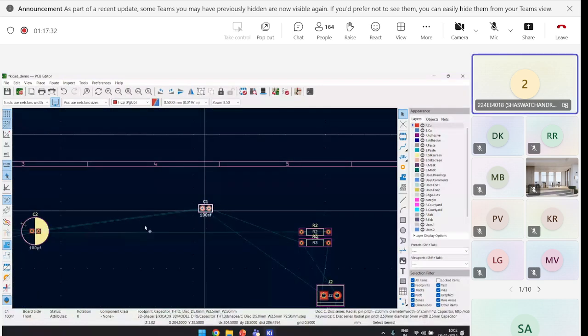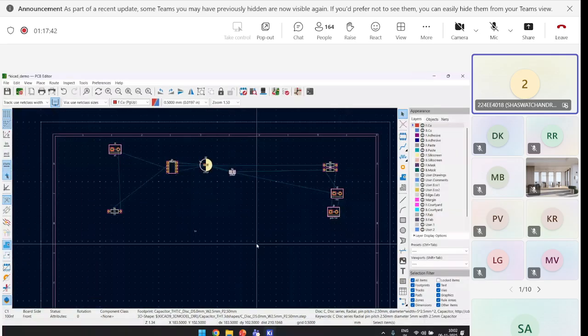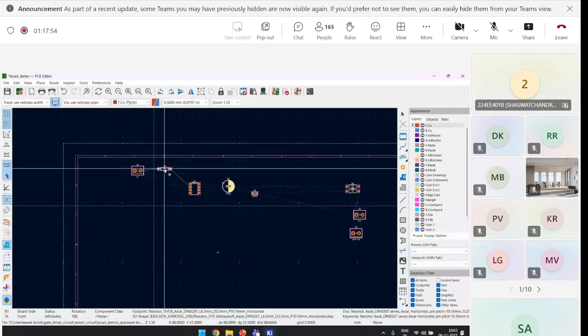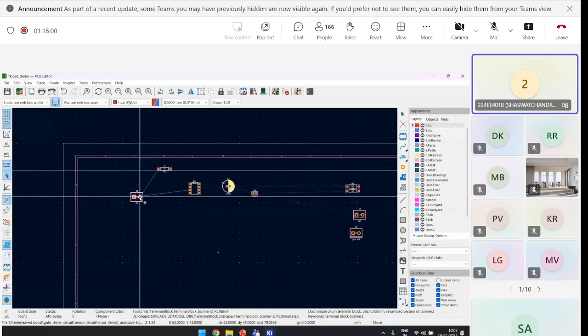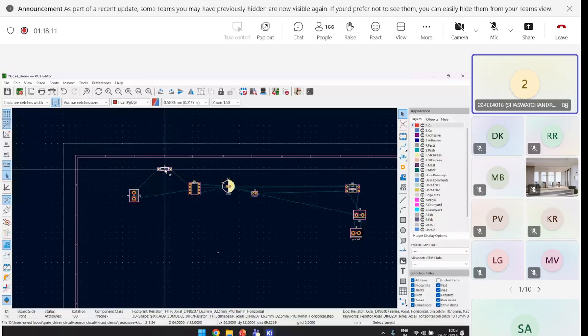So this portion of circuit design entirely depends on you, how you can optimize the placement of components and how you can minimize the required area. Here, you can click on each symbol and press R to rotate them. I'll be placing it here like this. The closer the better, because we want to minimize the area and make the circuit more compact. So I'll be placing them like this.